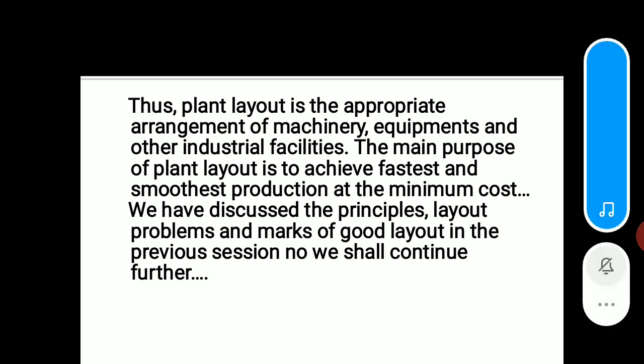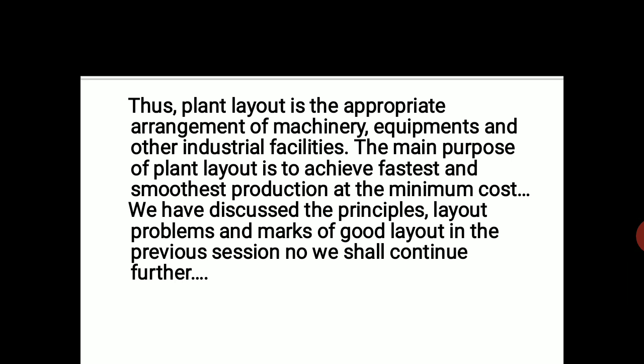So here what is important is the product and nothing else, whereas in the process layout, the similar performing machines are grouped together. You have a kind of section or department in which the similar functional machines are placed and they are performing, and of course they are placed in a sequence. That means department 1, then 2, then 3, and likewise.